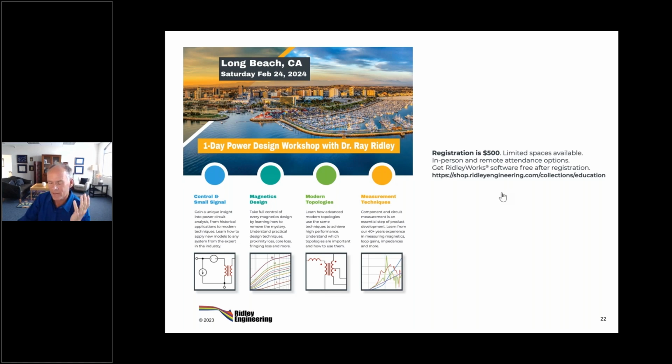And it really comes down to the control chip. How complex are you making that control chip model? We don't want transistor level control chips in our models. So we have behavioral models. So when you do that, LTspice is just fine. But PSIM is nice that it will give you that blazing speed. So for large systems, motor drives, things like that, it's really nice to have it.